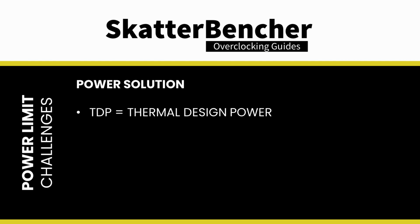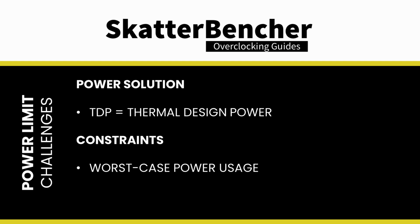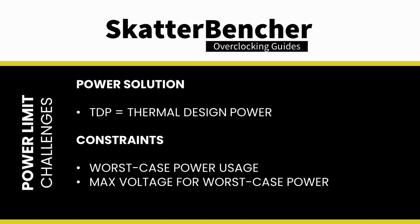Semiconductor companies like AMD address this challenge by utilizing a TDP, or thermal design power, limit. The TDP captures the maximum power a product can reliably operate at within the warranty period. The voltage and clock speeds selected for the highest power state are therefore limited by 1. The worst case scenario for peak power use, 2. The maximum voltage that fits within the power budget, and 3. The highest frequency that the GPU can run given that voltage.